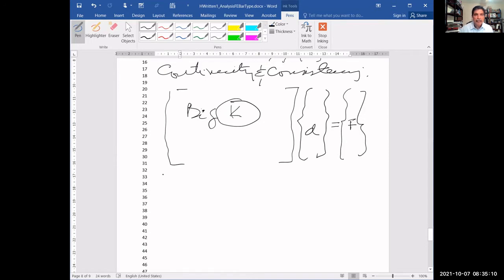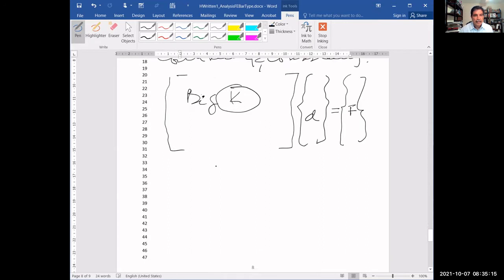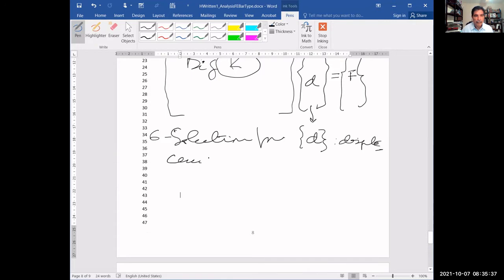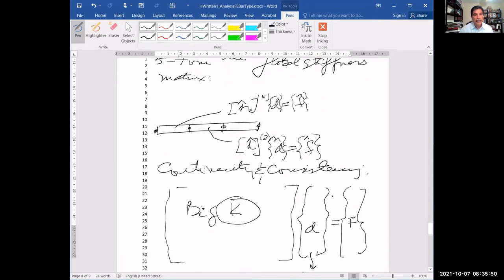And then the next step, the 6th. Of course, it's a solution. What we do is we find the displacements of every joint. When you solve this, you know how much this moves, this, and that. Now, we have to go back. Why? Because we want to know how much are the stresses here. And for that, we need to evaluate bending moment and shear forces, right?